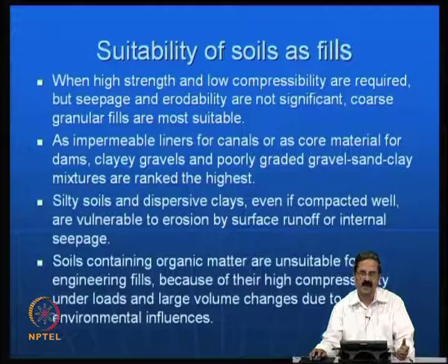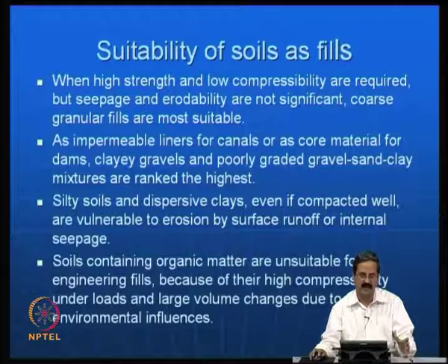In canal linings, the problem is that seepage should not occur and the water should not be lost in seepage, because it should reach a particular destination. So, it should serve as an impermeable substance to the extent possible, and also as a core of dams. In dams, the central portion is an impermeable membrane or sometimes a clay liner.